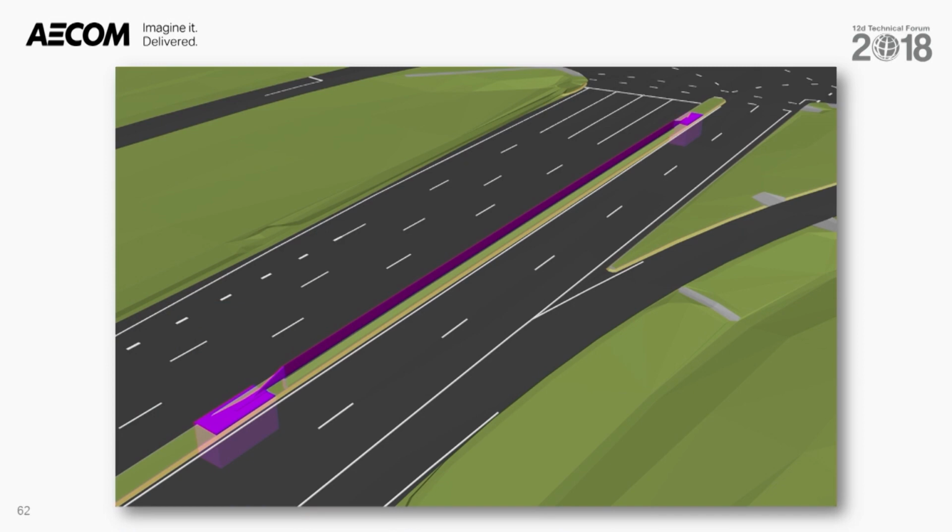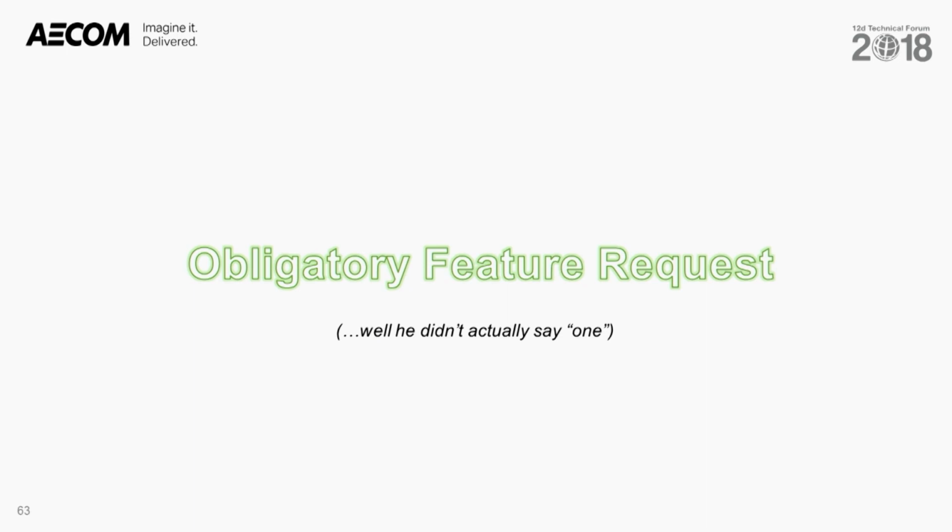What makes this object different from the light post shown earlier is firstly that the holding symbol needs to be applied to the end of the model wire rope safety barrier string. And secondly, the orientation of the symbol needs to match that of the string terminal. This is currently not a standard feature in 12D. So we've had to resort to a custom macro to place this symbol.